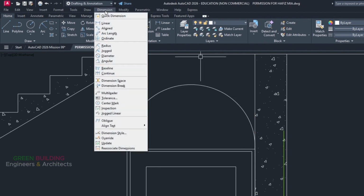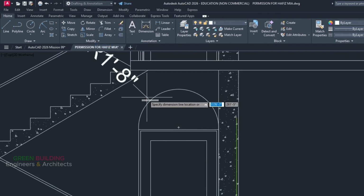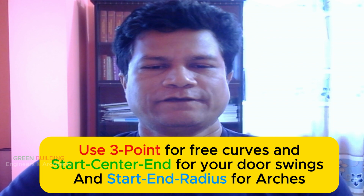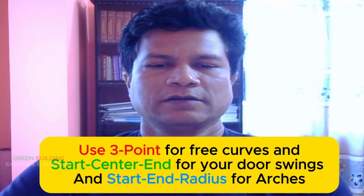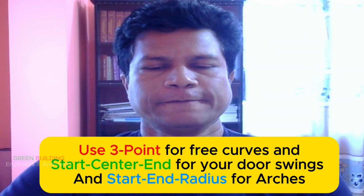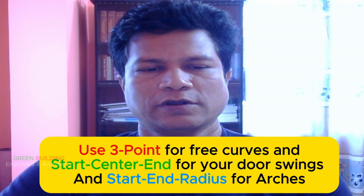Check the radius. One foot 8 inch means 20 inch. In this way, you can draw an arc using the start and radius method. To summarize, use 3 points for free curves like gardening, start, center, end point for your door swing, and start and radius for your arch.